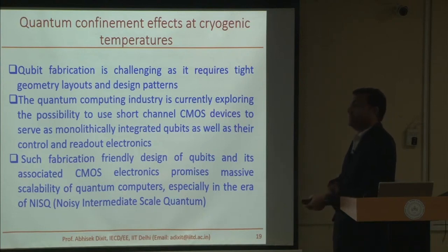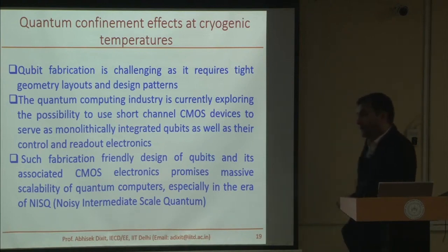Of course, we have 7 nanometer node, 5 nanometer node available. So people are doing it, but how are they doing it? They are doing it with the LE approach, right? Litho-etch. So you are doing multiple exposures, multiple etch steps to come down to that pitch, right? So for an industry, for a commercial flow, it is far more optimized and far more suitable to do. But for a research group to do that kind of multiple exposures to reach this kind of pitch is extremely difficult. So the majority of them are taking E-beam to their help.